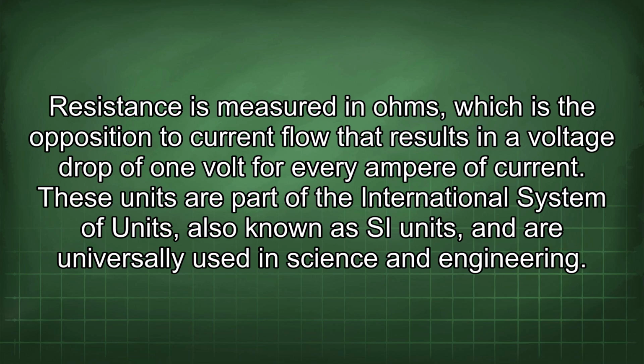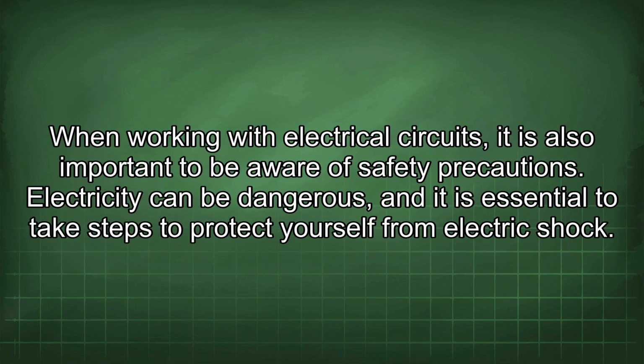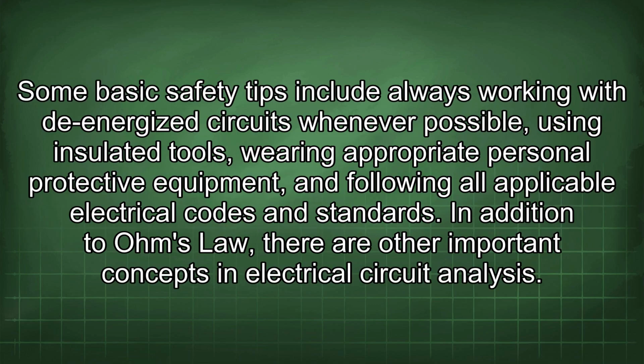When working with electrical circuits, it is also important to be aware of safety precautions. Electricity can be dangerous, and it is essential to take steps to protect yourself from electric shock. Some basic safety tips include always working with de-energized circuits whenever possible, using insulated tools, wearing appropriate personal protective equipment, and following all applicable electrical codes and standards.